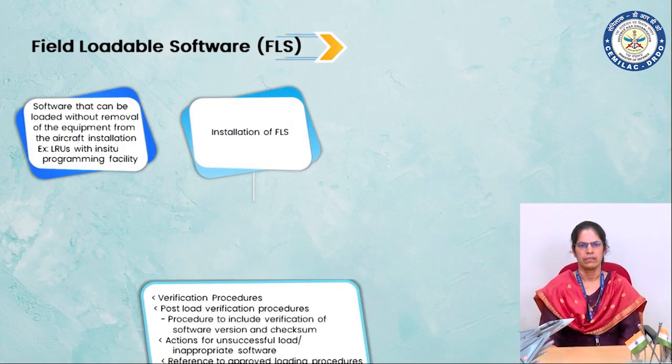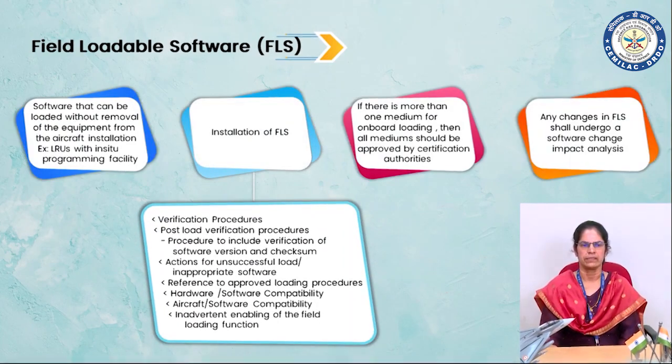Another topic in additional considerations for DO178C includes field loadable software. Software that can be loaded without removal of the equipment from the aircraft. For example, LRUs which are having in-situ programming facility. For field loadable software, we have to verify that post-load verification procedures are available. Actions for identifying of unsuccessful load or inappropriate software has to be available.